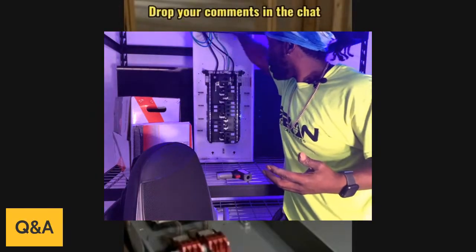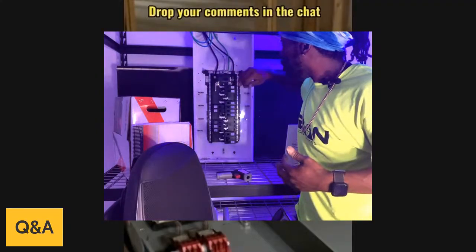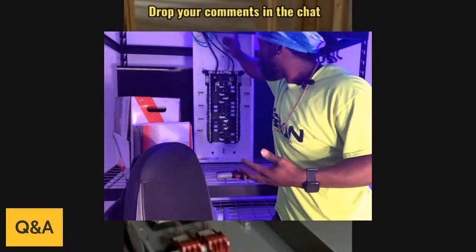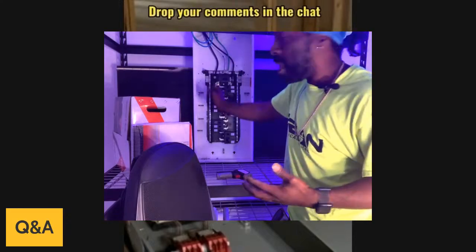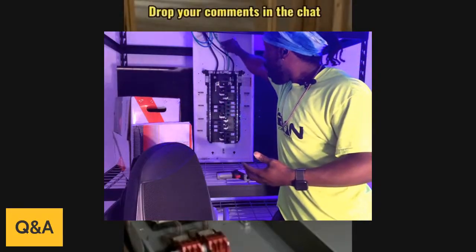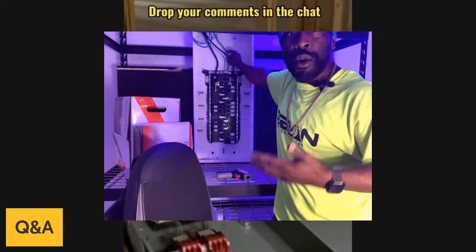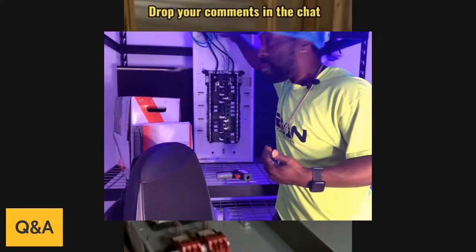Okay, and as you can see, if you're coming into here, you have to use Romex. You also have to make sure that when you're dealing with your wires, your bonding wire and so on, you're coming from the top of the panel and it's going into the top. It's not coming from the side. That will make you fail inspection instantly. So copper, you cannot have a bare copper coming in from the top. It has to be a solid green wire or it's going to be taped. And also, you have to come in from the top.